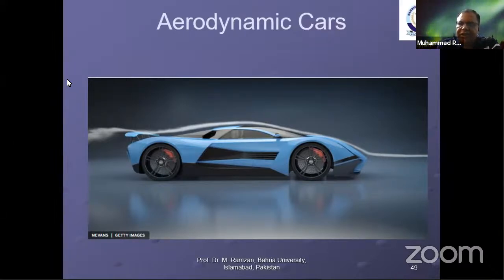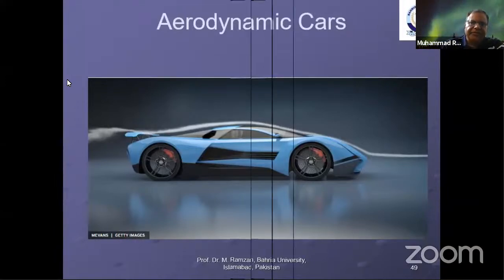This fact is partly due to the large radiator in front of the engine, positioned to maximize the cooling effect of the oncoming air. The use of nanofluids as coolants would allow for smaller size and better positioning of the radiators, owing to the fact that there would be less fluid due to higher efficiency. Coolant pumps could be shrunk and truck engines could be operated at higher temperatures, allowing for more horsepower while still meeting emission standards.